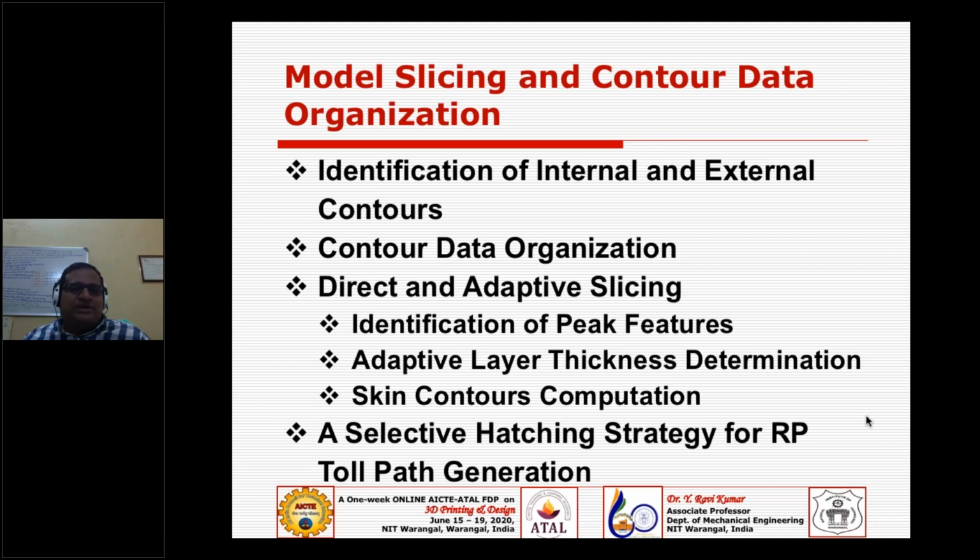This is 2D printing, but at a time you are printing only on the plane, that is 2D only, or 2.5D with a uniform layer thickness. Each layer is a 2.5D. So you generate your tool path, or a movement of xy, the coordinate of xy of your polyline.